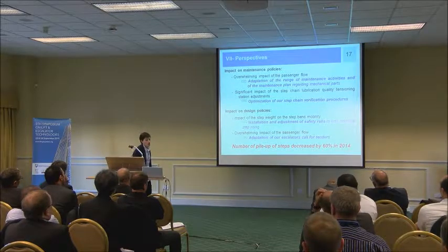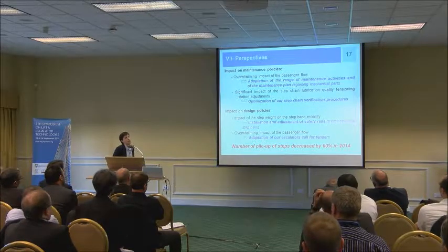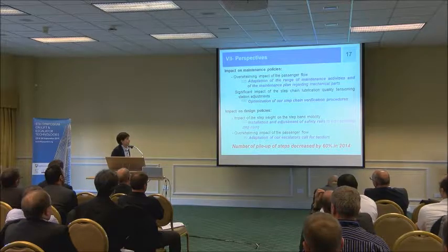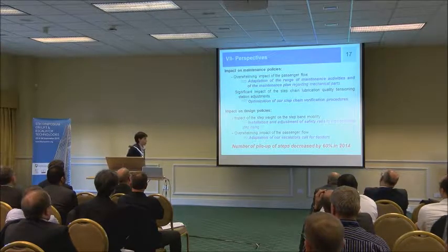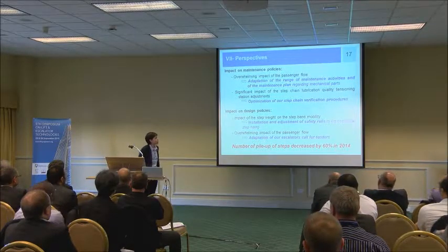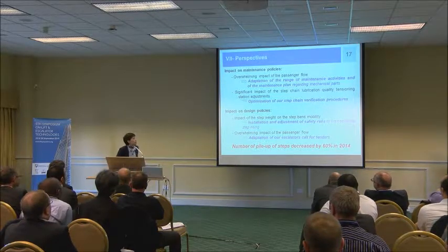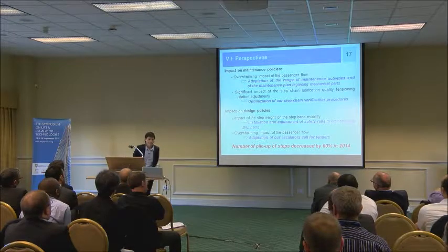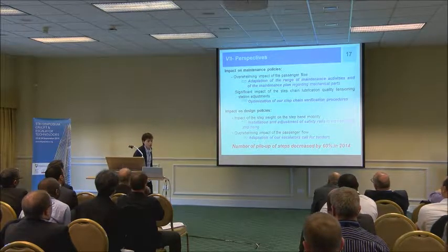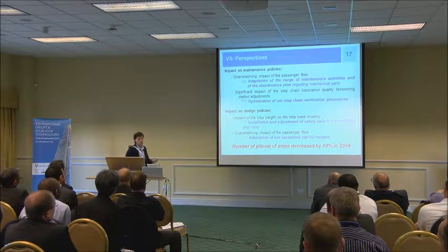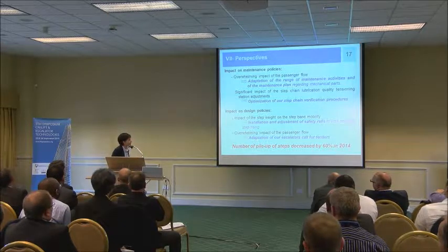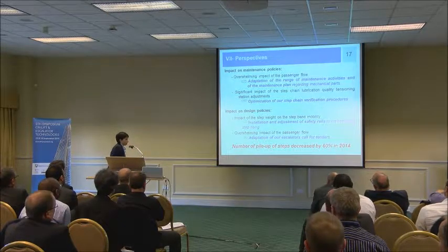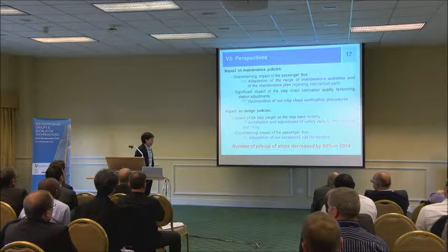We also optimized our verification procedure of the tensioning station and step chain lubrication. We installed or readjusted safety rails to prevent any step rising.